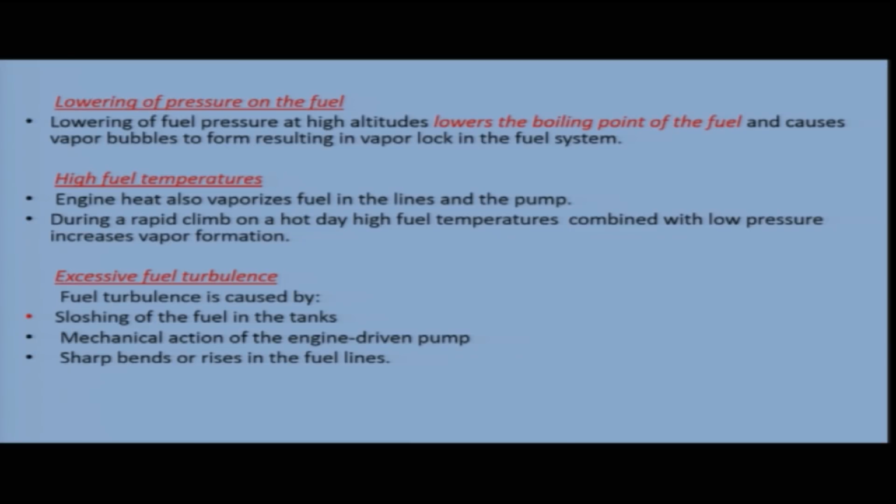So, at high altitudes, when the fuel pressure is lowered, it lowers the boiling point of the fuel and causes vapor bubbles to form, resulting in vapor lock in the fuel system.